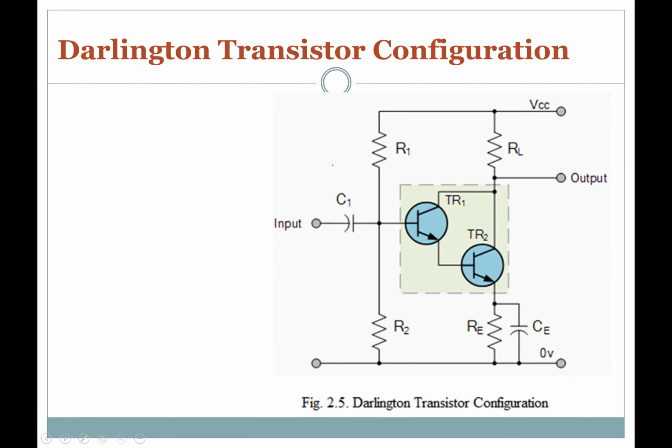Now, one thing that happens with Class A amplifiers is that they can easily get overheated because of the high power dissipation. You remember we said there is wastage of power. So one of the ways of improving the Class A amplifier's current handling ability is the use of a heat sink.